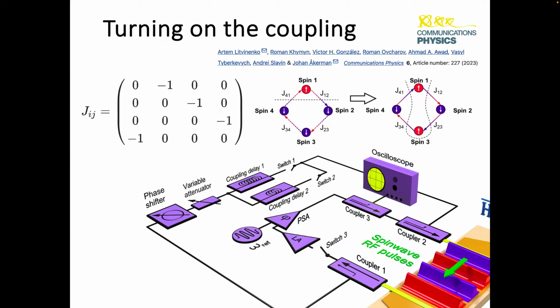So when a pulse is injected here, we siphon off 10%, let it delay 1 pulse transmission, get it back into a coupler here, where we again just take 10% of it and combine it with another picked up pulse here, and those 2 energies then add at this point.